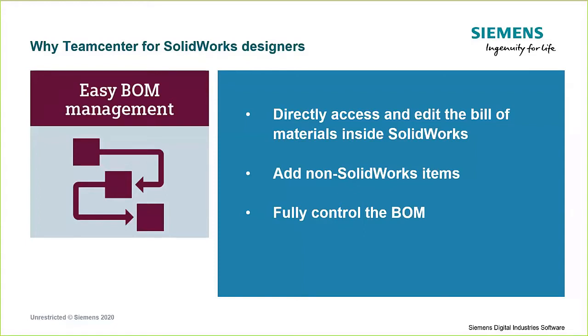And what we typically see users doing is they just put a part in SolidWorks, but they don't add any geometry to it. So it's in essence a blank, no geometry part. Well, what about name BOMs? Name BOMs, you can generate those via Windows Explorer. But keeping that name BOM connected to your CAD BOM, once again, can be difficult and cumbersome.